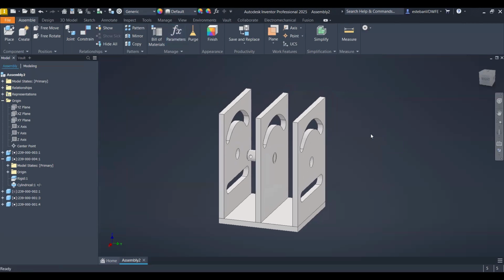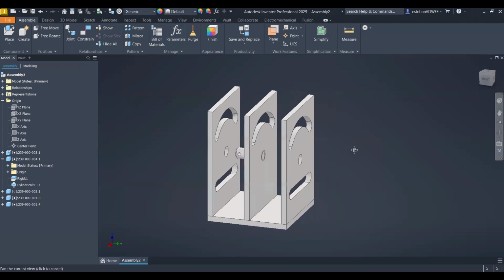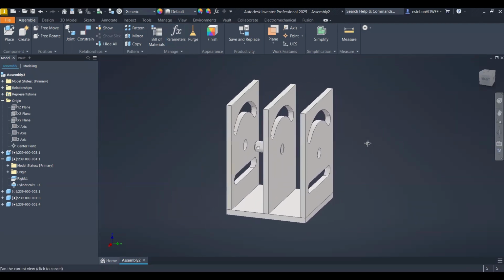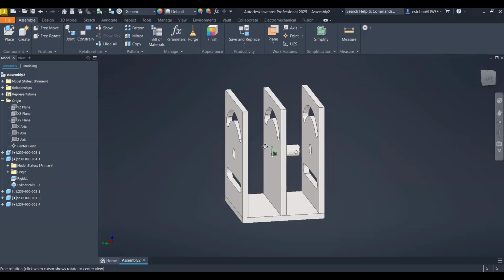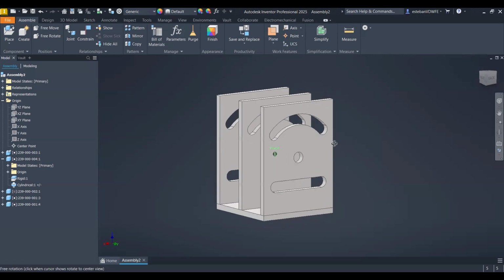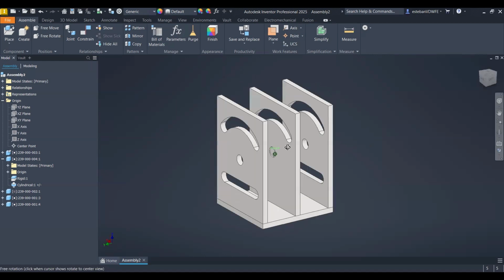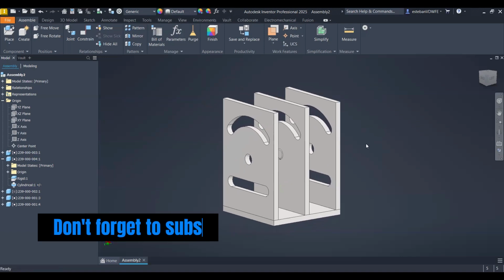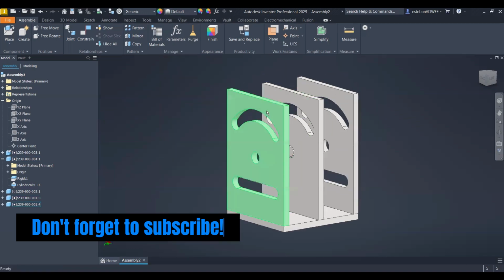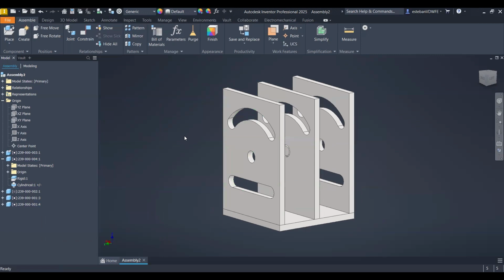And just in case this is the first time you see this program and you have not noticed, when you click the scroll, the thing is doing the pan, not rotating as in SolidWorks. You need to hold the shift key on your keyboard and just click holding the scroll, and then you have the rotation that you are expecting, just in case. Some critiques for Autodesk: they are doing many things, improving many things on Fusion, and do not including them in Autodesk Inventor. They have in Fusion the option to select the preset of the buttons on the mouse, so they have the option to rotate as in SolidWorks. I don't know why they are not providing this option in this program, which is amazing, to be honest.